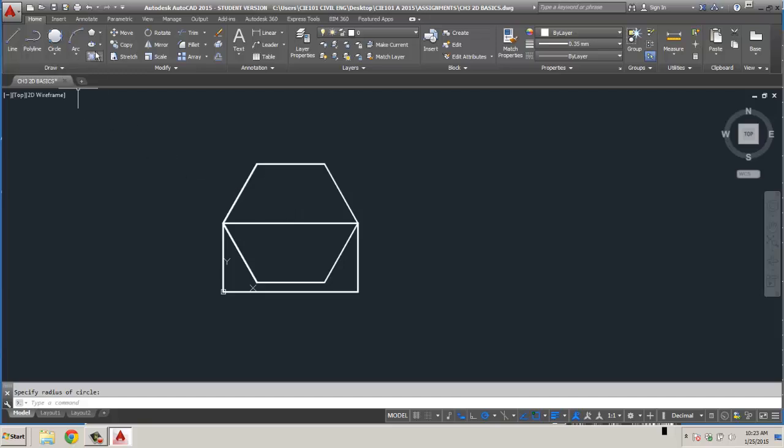Let's do the same thing now. Number of sides, let's put 7. And center point. Now, do you want inscribed or circumscribed? Let's go with circumscribed. And now we come out to this point. You'll notice it goes to the flats. So an imaginary circle would go on the outside of this one. So you can see the difference, now the flats would actually make that imaginary circle.